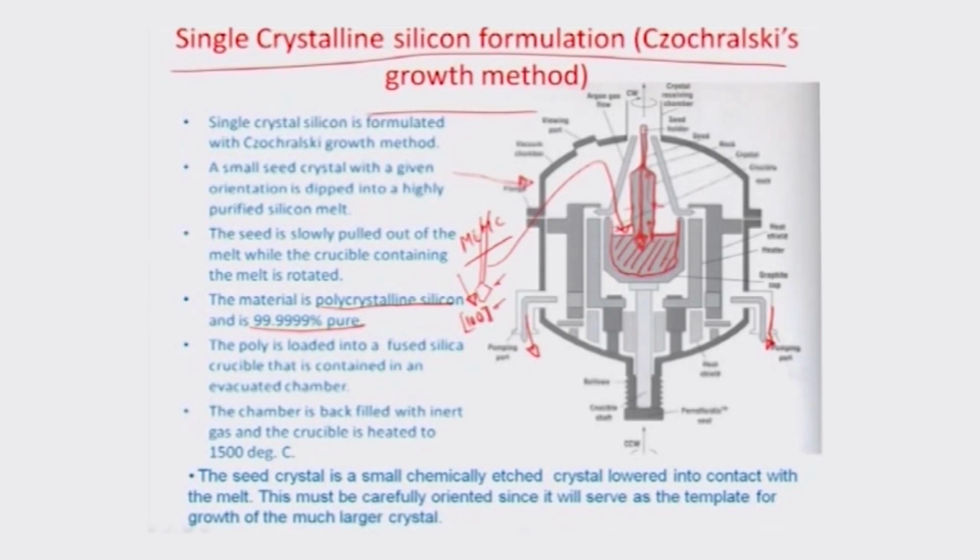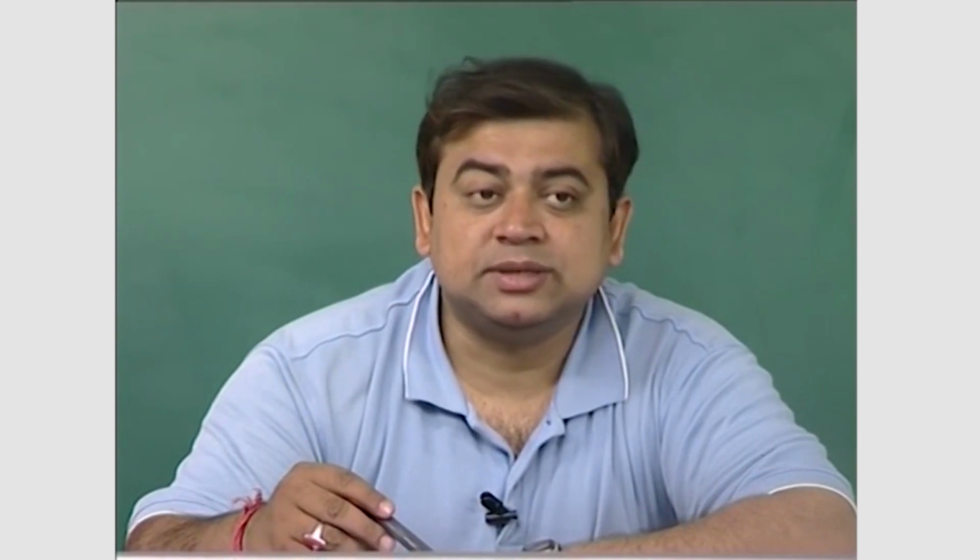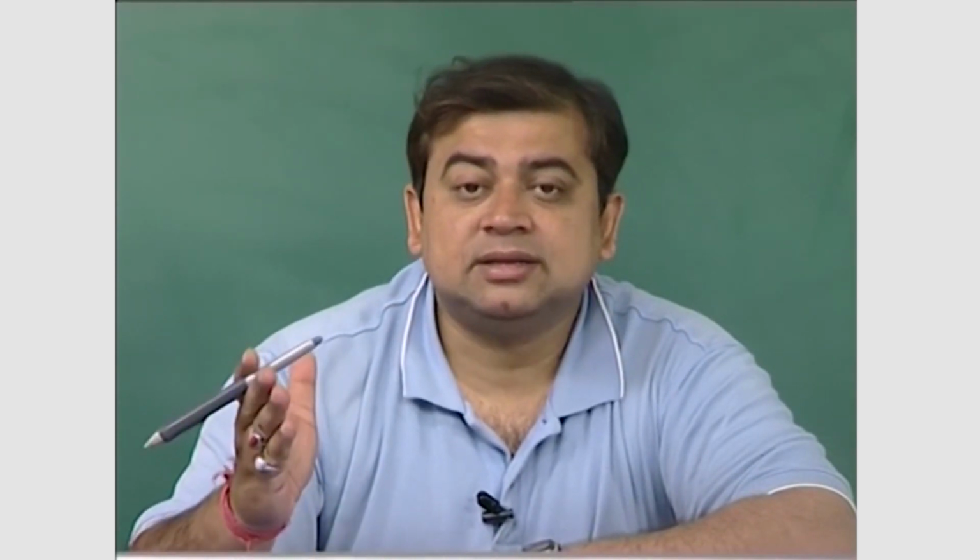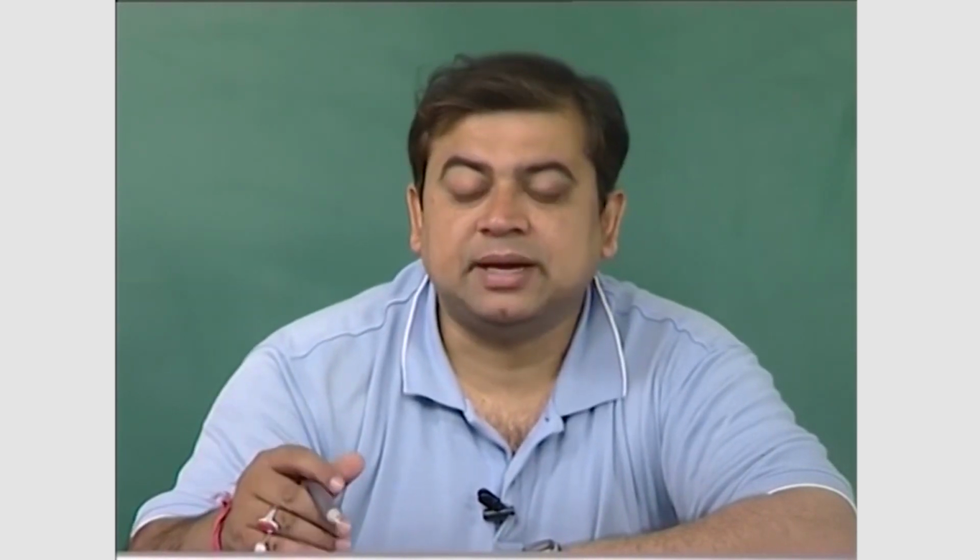cut this boule into pieces, and you can fine polish them, and there are a lot of methodologies like CNC wire cut EDM or some other instruments which are used for fine sizing, or maybe even a band saw, which are used for fine sizing these wafers. Typically, these wafers can vary between 400 microns thickness to about 900 microns thickness.